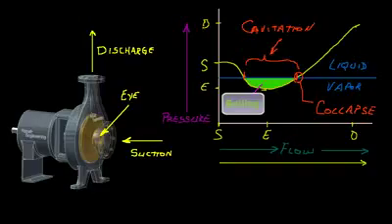You might be wondering how all of that damage that we saw earlier could be caused by having gas bubbles in the fluid. And the answer to that is, for the most part, the damage is not caused by the gas bubbles themselves, but by the collapse of the gas bubbles at this point of the process.